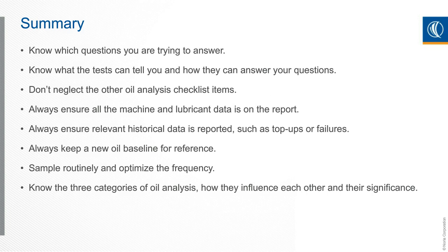That way, the oil analysis laboratory technicians can properly figure out whether or not that result that's showing could make sense or not. Always ensure relevant historical data, such as top-ups or recent failures potentially, are in the oil analysis report so they can use that data.